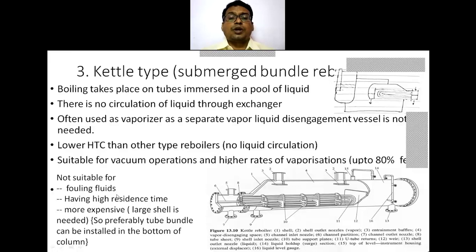It is not suitable for fouling fluids because the velocities are low. We are using the fluid on the shell side, so velocities are low. When the velocities are low, scale formation or fouling will be more.